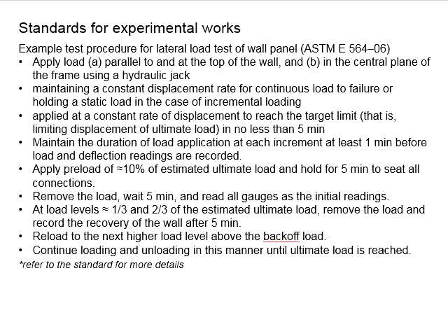If you are conducting the testing by the constant displacement rate, you will need to make sure that it takes not less than 5 minutes to reach the target limit, that is the limiting displacement at the ultimate load. That means this entire testing, if you use the constant displacement rate, must take longer than 5 minutes. It shouldn't be too fast, as this is going to influence the ultimate capacity due to the inability of the stress to be properly distributed within the structural element that can lead to premature failure of the specimen.